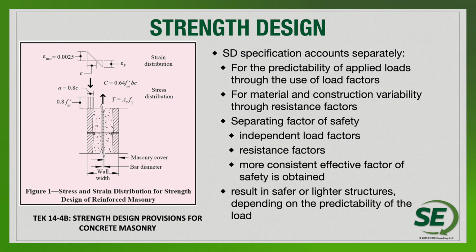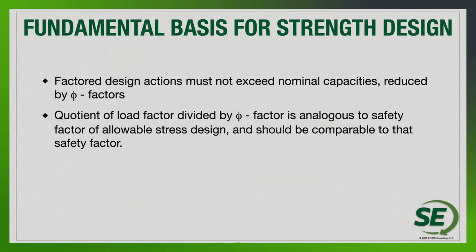Obviously, things that are going to be governed more by dead load design situations can certainly have a lower factor on those elements. You could have a much lighter, more efficient design. Stuff that's going to be governed more by the transient loads, the live loads, the wind or seismic loads, if those are going to be more of the primary elements, then certainly it's going to be a safer design, I would think, for strength design. So it tries to put more importance on the less predictable load situation.